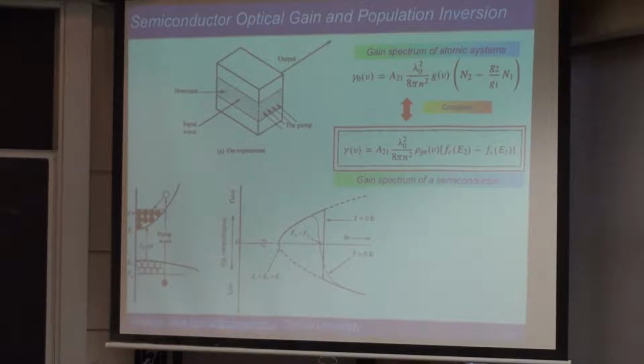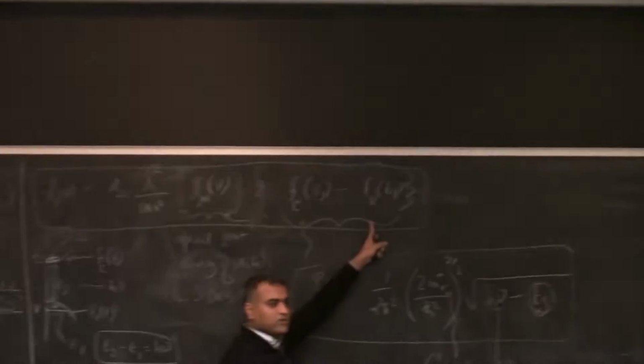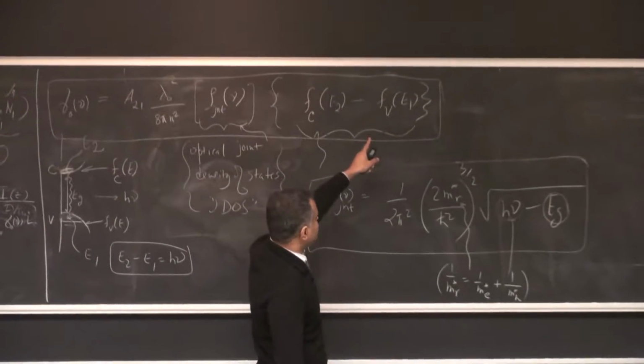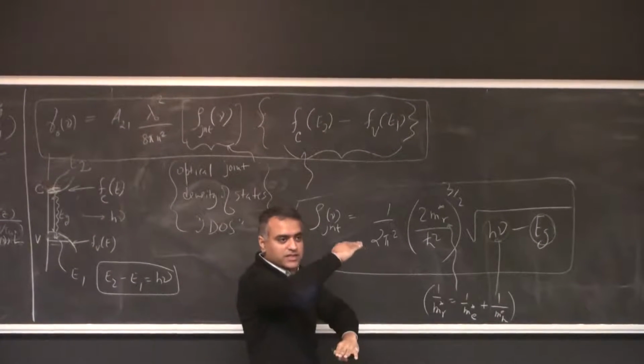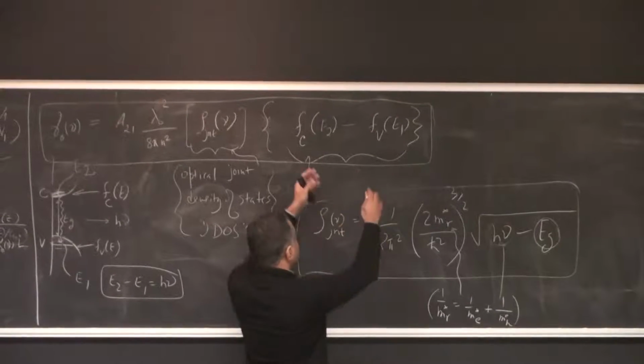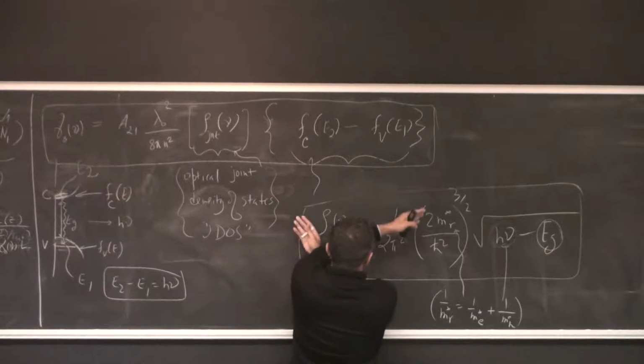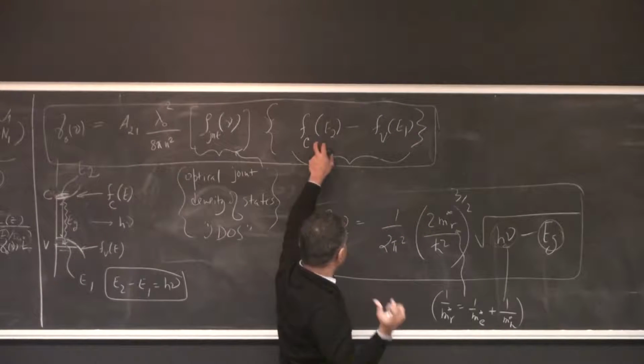And then you connect your battery to the semiconductor laser diode, and when we apply our voltage across the battery, we are tweaking these two directly. Every volt of battery voltage we apply, we are moving one of the Fermi functions one eV above the other. So that's what you're doing. So you go from like -1 all the way to +1. You tweak it completely such that you get population inversion.